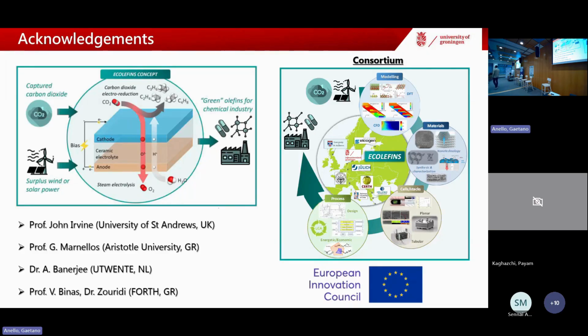How do you fabricate your electrodes? Screen printing? The powders, classical. No, the cell. The cell I cannot disclose exactly, but it's quite basic. We make the pellet, the green pellet. We cast the electrolyte, and then we co-sinter at a very high temperature, and then we start the process with the barium stuff. But we have special ways to treat it because the barium can evaporate quite easily.